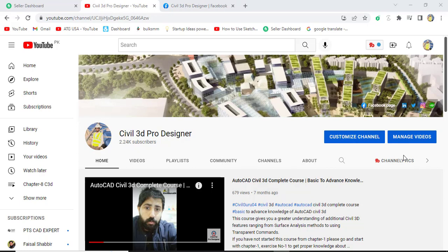An assembly is a representation of the cross-sectional geometry of the feature which we are designing. It establishes the overall shape of the cross section and distinguishes the areas within it. For example, a typical road cross section can have areas of asphalt, pavements, base materials, curbs, and sidewalk. So all these things combine in an assembly to make a typical section for the road.